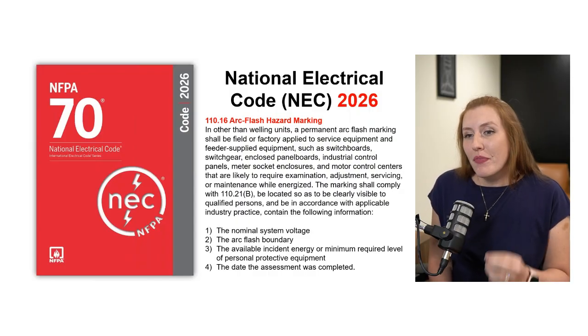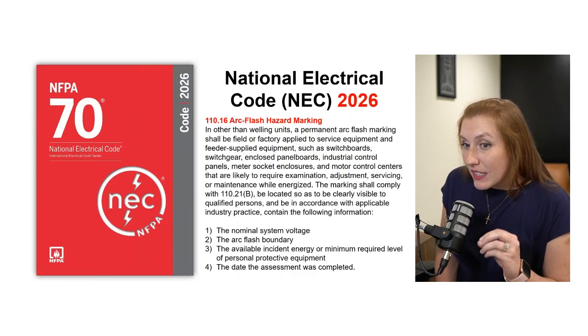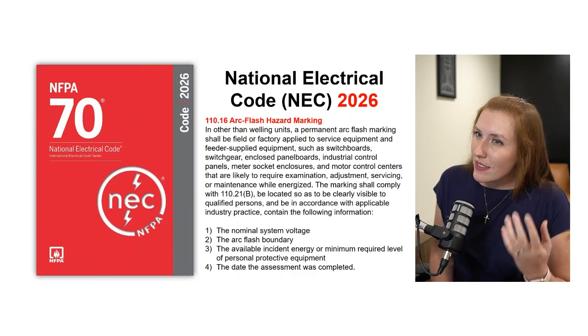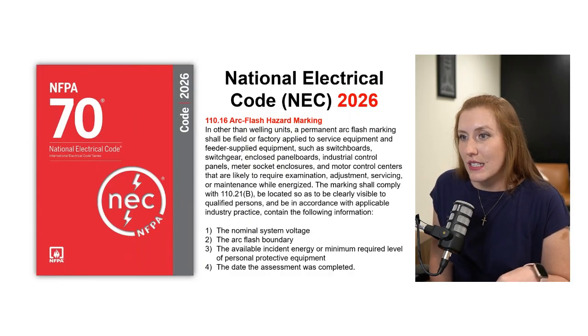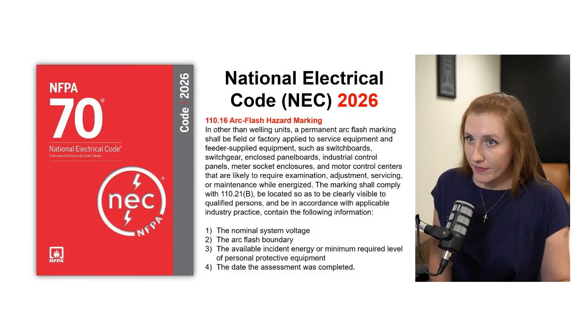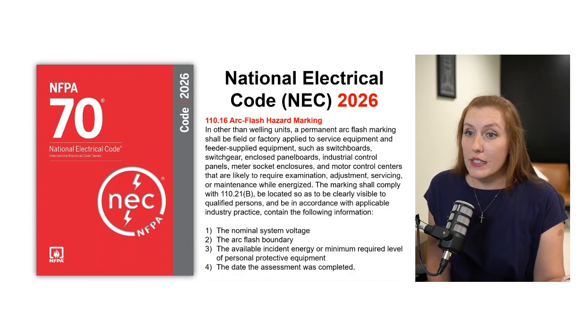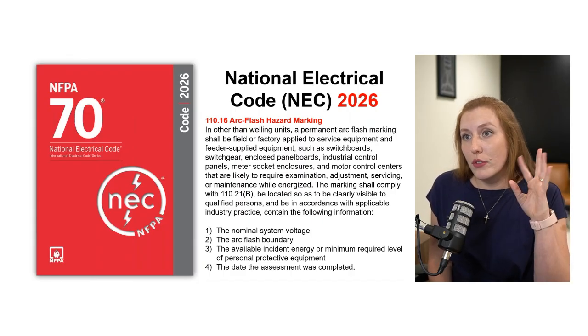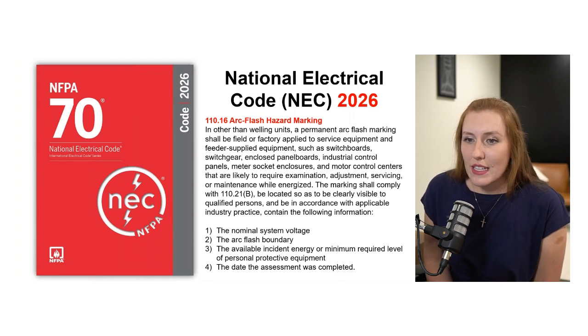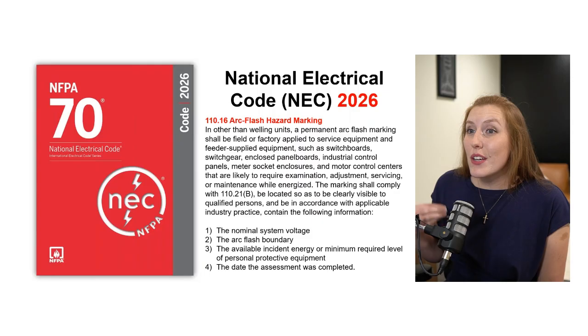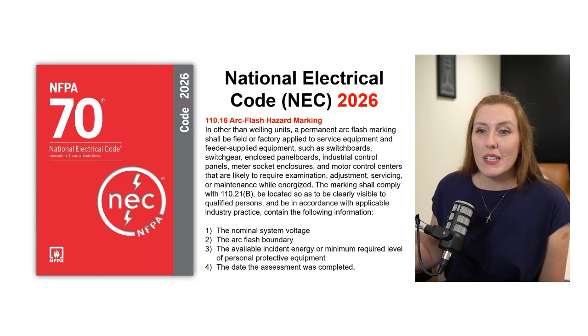One piece of information that is very specific here that wasn't necessarily included previously was the date that the assessment was completed. Now, this is important because, as we know, arc flash studies need to be reviewed at a minimum of every 5 years, and there's other reasons that that date is helpful as well, but now it is required.